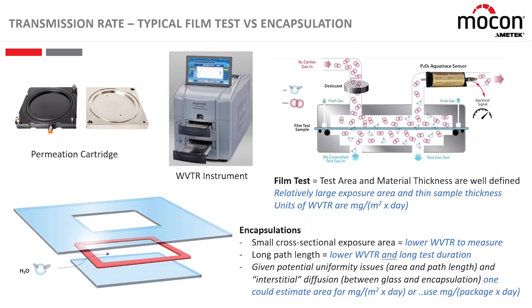So let's talk about permeation testing. How do we do it? How do we handle it? A typical test that's done is on a flat film structure. It's a barrier material. So what we saw on that first diagram, with all these molecules on one side, a barrier material, and the low concentration on the other side, we're going to mimic when we set up a sample. Typically we'll have a material that's roughly 4 by 4 inch square.